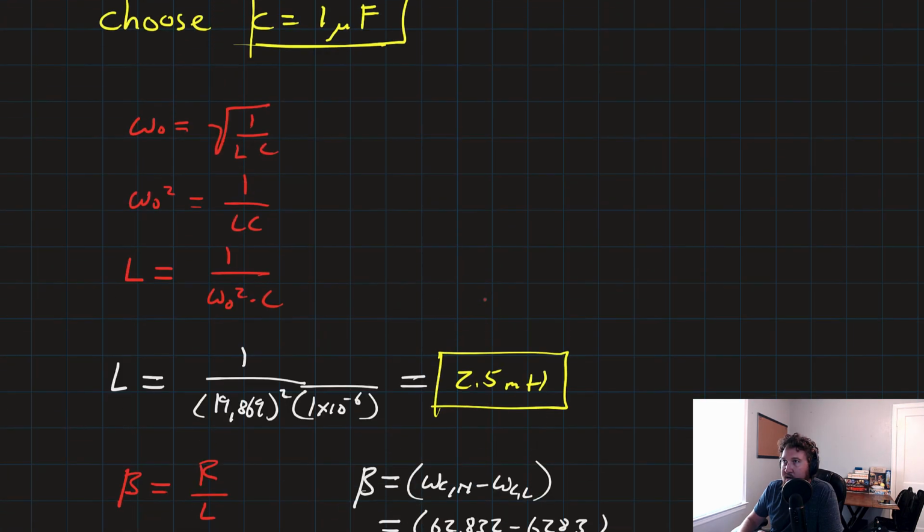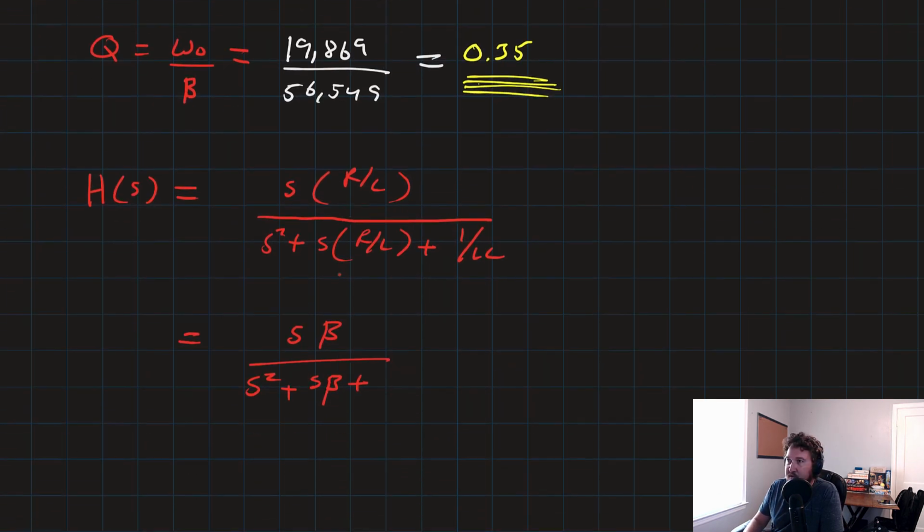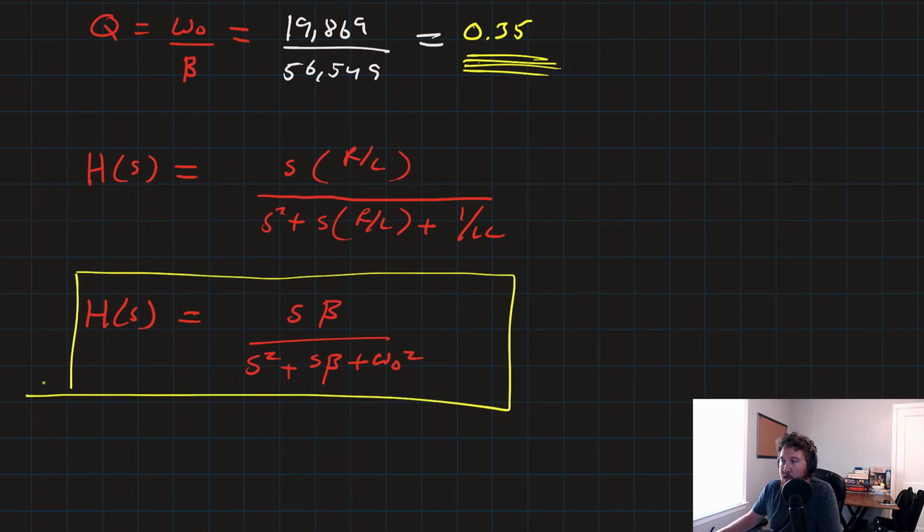What was that? Square root. Look at that. The cutoff frequency, omega naught, is the square root of 1 over LC, which means that 1 over LC is just going to be the center frequency squared. So there we go. There's a much more concise way of writing our transfer function.